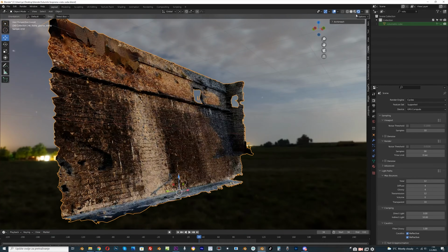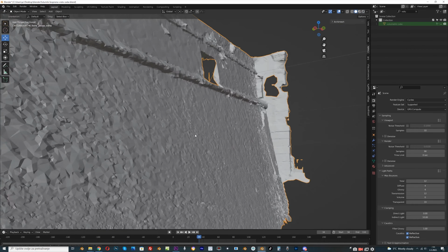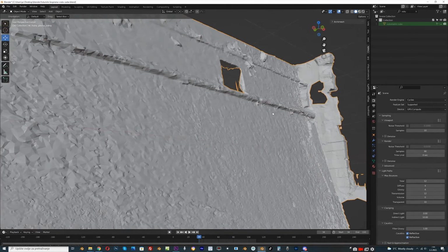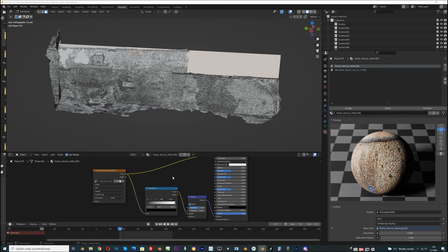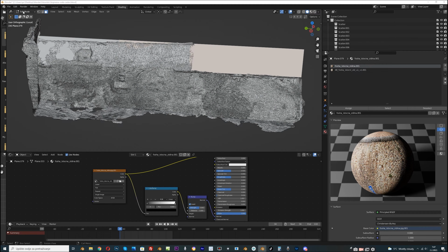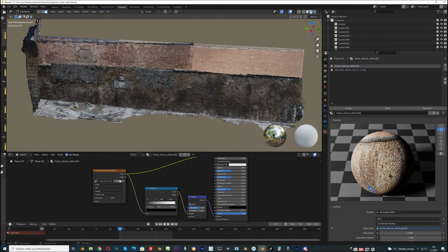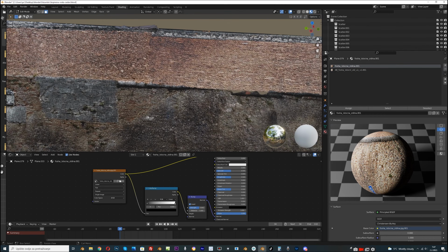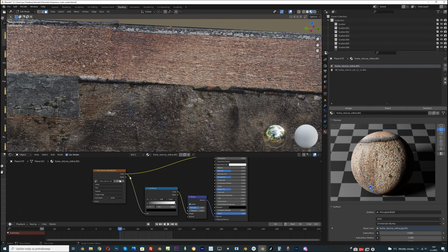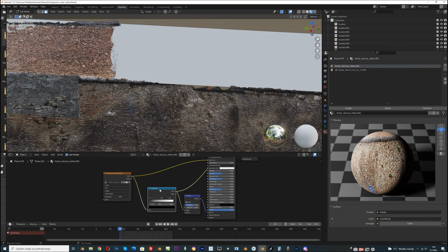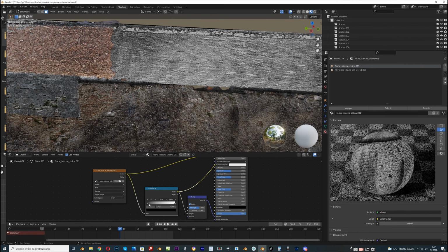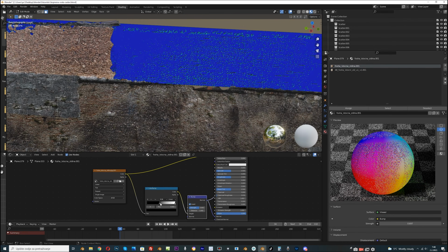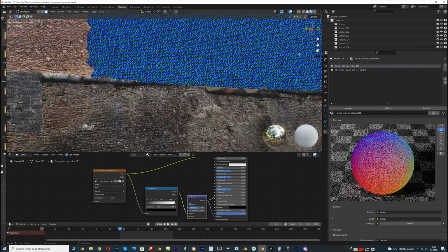With photo scanning we get a complete relief, and we can try to copy this with bump and displacement maps, but less successfully. Bump and displacement works by creating a relief based on the white and black colors. For example, if our stone is black because it's dirty, Blender will hollow it out instead of bulging it. And we also get the perfect UV map with photo scanning.